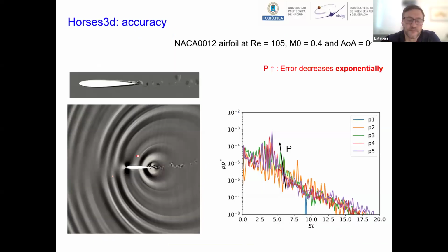Now, if you go into acoustics, what's perhaps interesting is that acoustics is a much more complicated problem, right? So what we need for acoustics is to properly capture what's happening in the boundary layer. All these vortices emanate, traveling through the boundary layer and impinging into the shear flow here, and then emanating sound waves. So for this, we need to capture well what's happening in the boundary layer, what's happening here at the trailing edge, and then how these traveling waves travel towards the observer, which in this case is here.